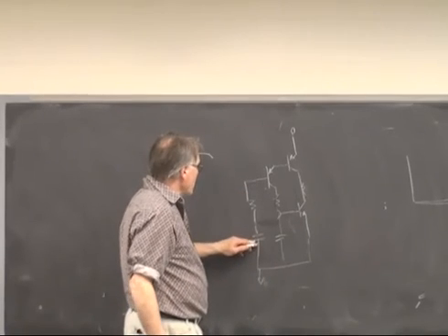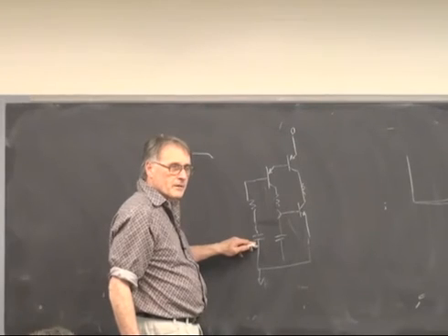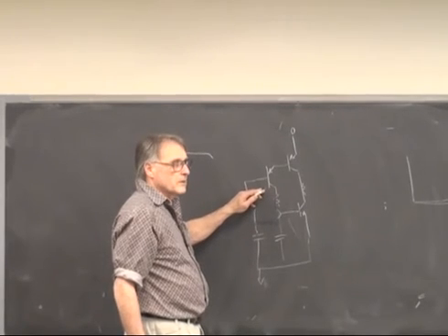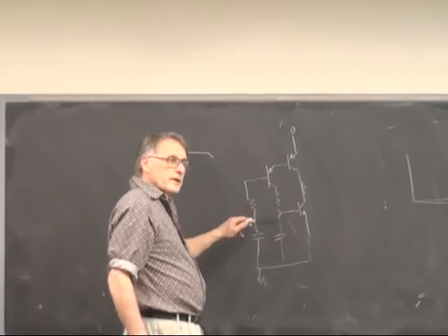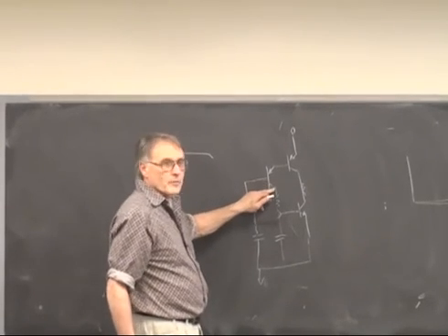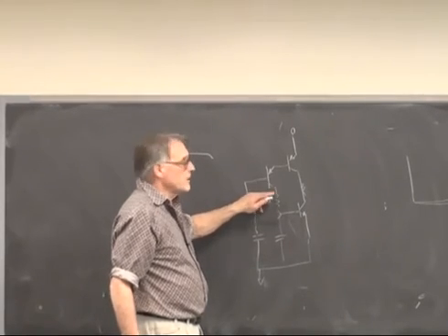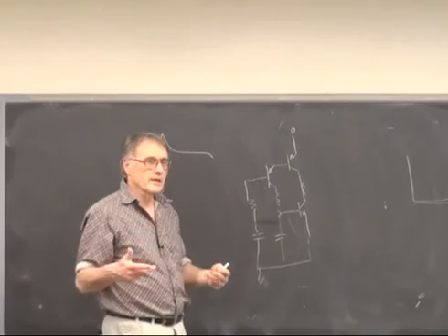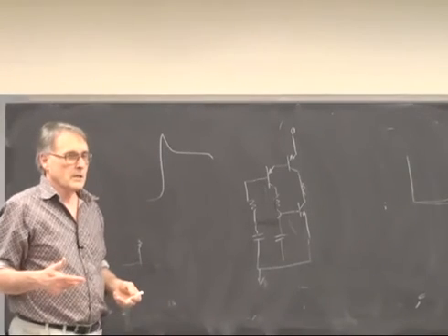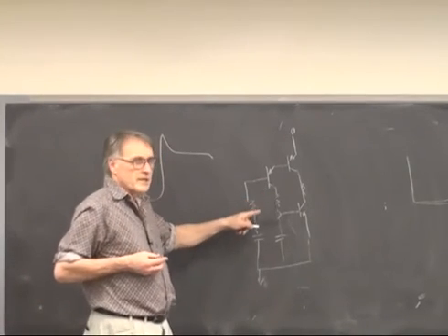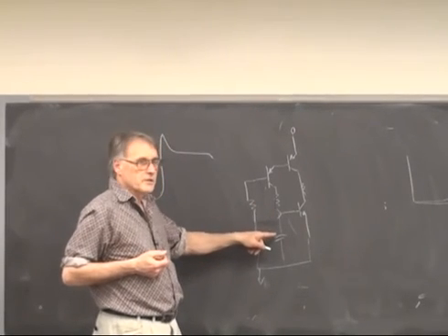This voltage would climb and never decrease because there's no DC path out of here. You could get into a situation where this junction is forward biased, which you don't want, right? The PN junction for the collector and the base always needs to be reverse biased. And I can't see how you could guarantee that would always be true here. It seems like these could charge at a different rate.